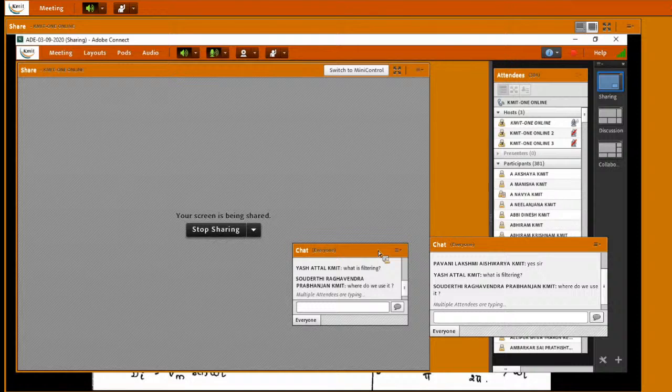If you directly connect a 230 volts AC source to digital electronics or any gadget, it is not going to tolerate it. So how do we convert AC to DC? The 230 volts AC is coming from outside, and we convert the 230 volts to 12 volts with the help of a transformer. The transformer steps down from 230 to 12 volts or so, but that is still an AC signal. Now, how to convert AC to DC? With the help of the rectifier circuit.